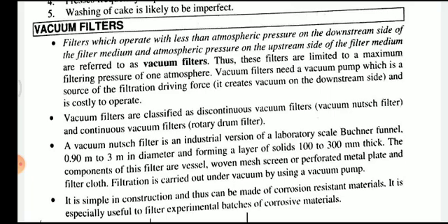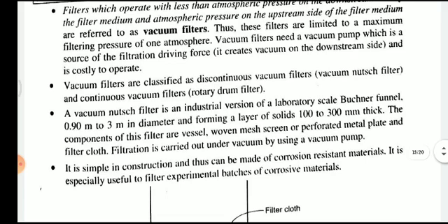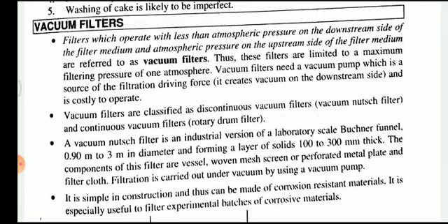That means above the filter medium the pressure is only atmospheric pressure, with no other pressure acting on it, and below the filter medium, the downstream side, the pressure is less than atmospheric pressure. So it is called a vacuum filter.